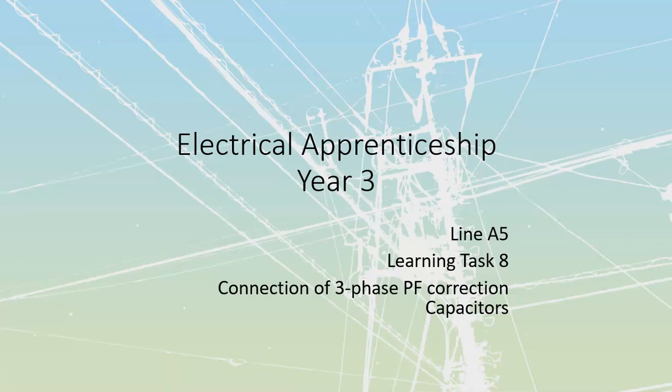In other cases, you're able to actually correct that. You can take power factor correction capacitors and drop your kVA back down, and it frees up a bunch more room on your system itself. We would like to have a unity power factor. However, there's very few things that actually run at a unity power factor.